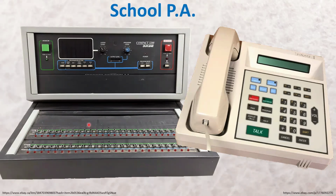Some of them are still in use. The newer ones would have a console like that. If a classroom is calling, you would get the display on this window right here, and you would use a handset to talk to a classroom. So, school PA systems. In fact, next week after this, we're going to do the PA system lab. That is going to involve that type of installation of the hallway speakers that would be interfaced with one of these.